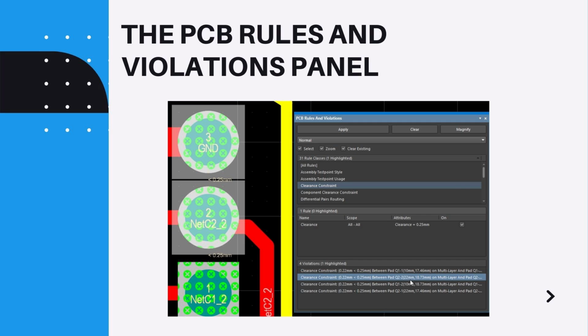Once you have identified a rule type of interest, select that specific rule so that only those violations are shown at the bottom of the panel. Then click once on a violation in the list to jump to that violation on the board. Double-click on a violation to open the violation details dialog. The panel details the violation type, the measured value, the rule setting, and the objects that are in violation.